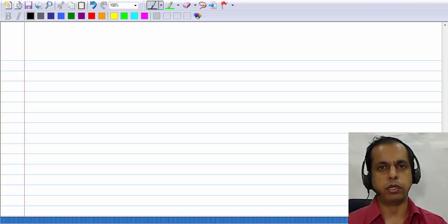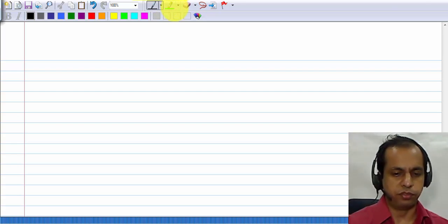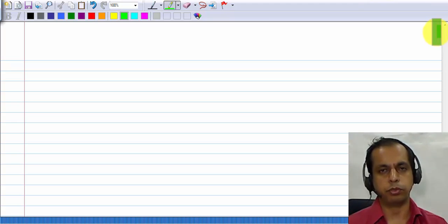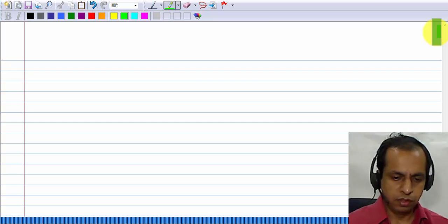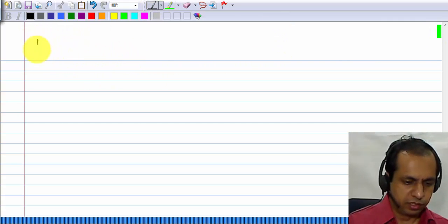The way you complete the feedback around a transistor, there is an endless variety, but we will take a few of them for illustration. And actually, these circuits will be useful not just for biasing. It turns out that if you apply inputs at the appropriate places and take the outputs at the appropriate places, you will also have useful functionality. So first let me consider drain feedback biasing.